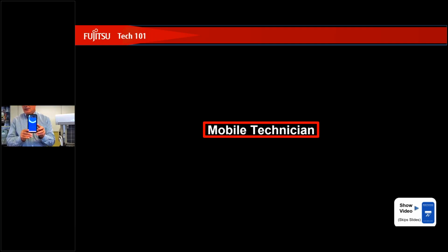The PT chart we use a lot because this is how we find out if I'm really charged correctly. And when I click PT chart, I'm going to see a 410A icon. And if I click on the 410A, and I put in my outdoor air temperature. So let's say for argument's sake right now, it's about 55 degrees. And I hit done. My outdoor unit, now if I put my gauges on there, I hope you can see that, should be sitting there at 156 PSI. And if my outdoor unit is not sitting there at that PSI, I have a charge issue.